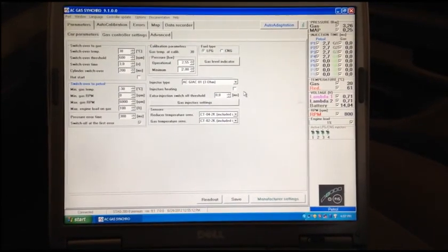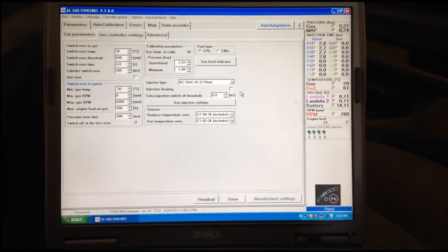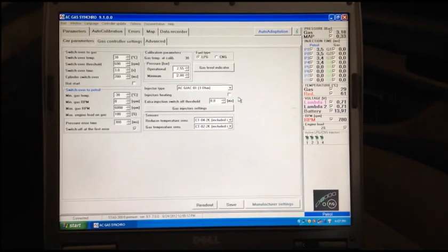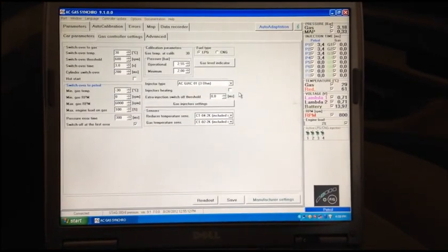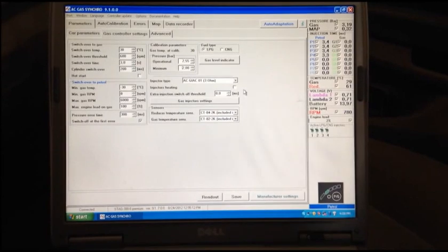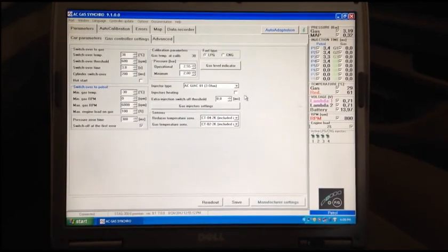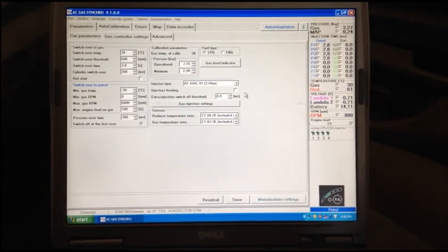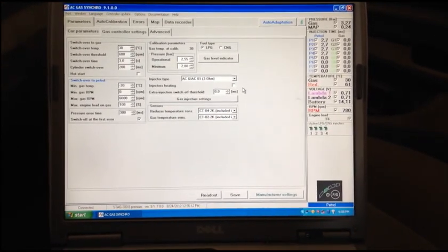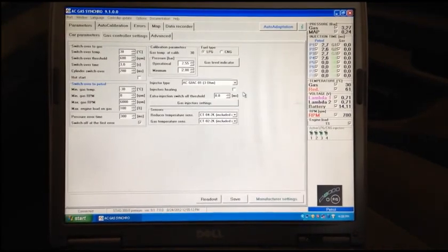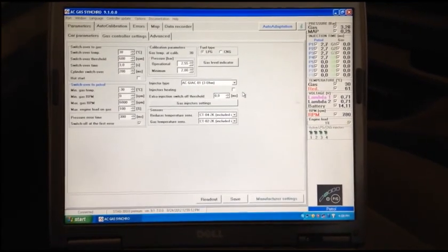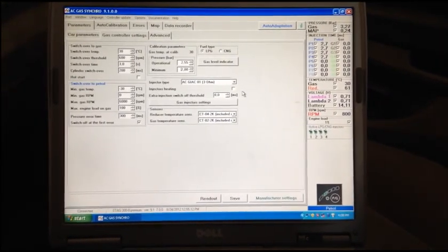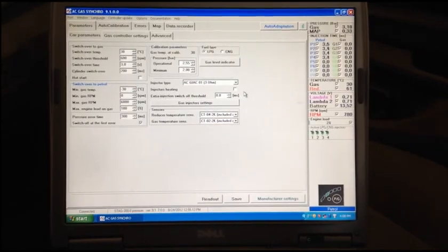Basically what happens is you have a little strategy, kind of like priming or an accelerator pump in a carburetor, built into some cars' ECUs on the gasoline injectors that sends a tiny little pulse before the main pulse of the injectors, and that pulse can be interpreted incorrectly by the CNG computer as an actual pulse. It will cause a situation where you've just tuned and everything looks right, all your settings are proper, but when you aggressively snap the throttle open, you get about a half-second bog.